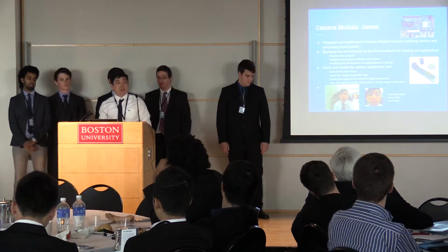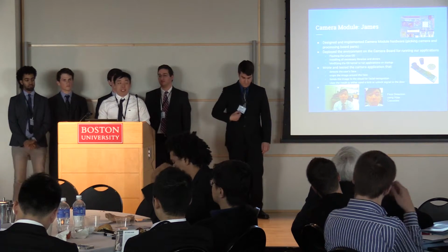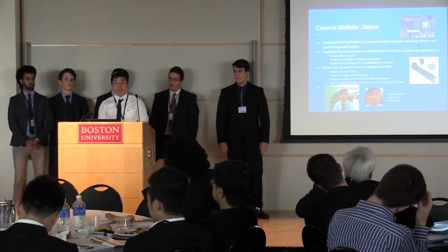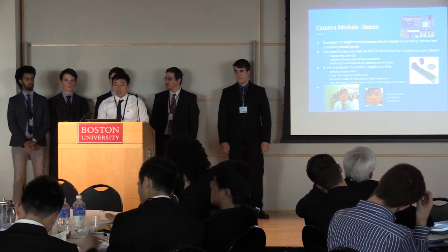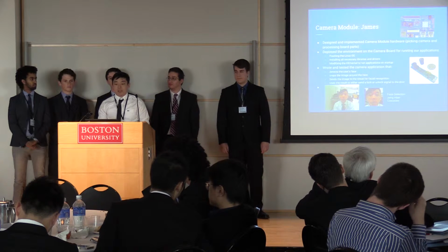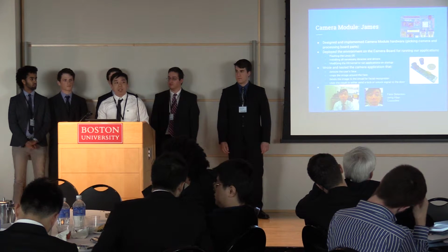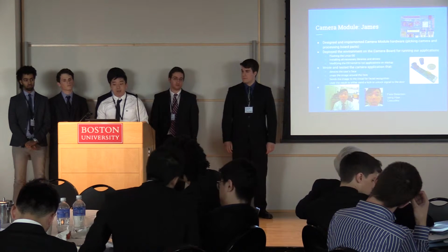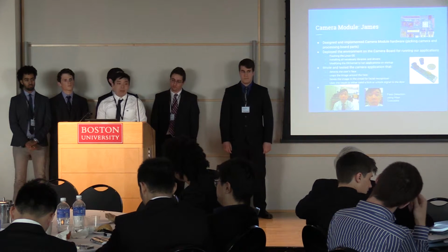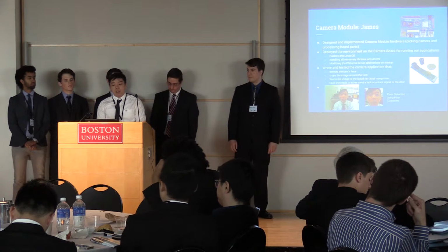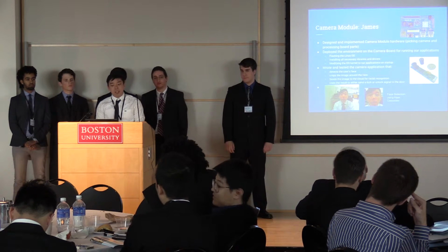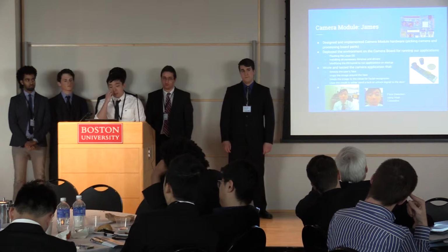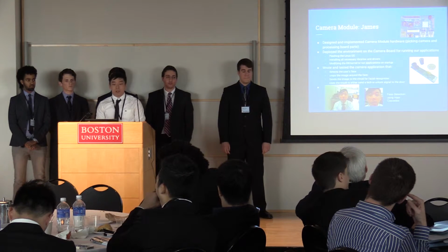I worked on the camera module hardware, which included designing and choosing the parts for the camera and the processing board that we would use it on. I was involved in deploying the environment on the camera board to allow for deploying our application on there, and I wrote and tested the camera application that goes through the pipeline of detecting the user's face, cropping the image around the face, sending the image to the cloud for facial recognition, and using that result to either send a lock or unlock signal to the door.